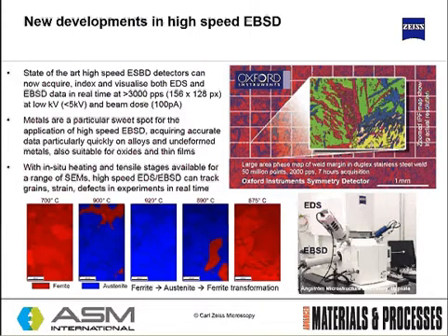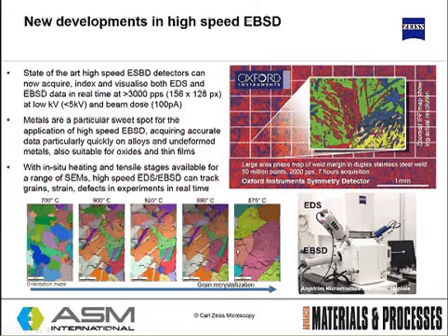We also covered the austenization and annealing of ferritic and austenitic stainless steel. You can see that with EBSD, you're able to determine the annealing temperature required to transform a ferritic stainless steel to an austenitic stainless steel. And then in this case, the temperature has been cooled gradually to transform back into a ferrite. You can also identify the grain crystallization, so the orientation maps of the particular ferritic and austenitic species and back to ferritic species, and then you can measure the grain parameters of that sample before and after annealing.